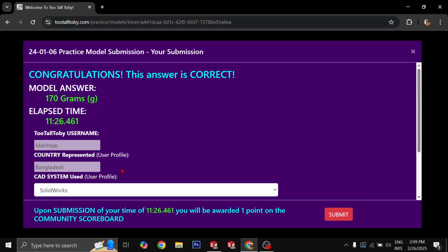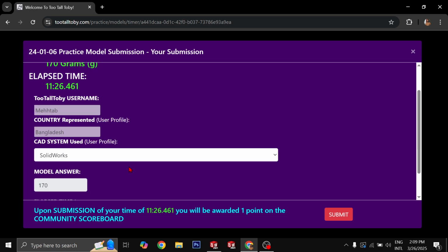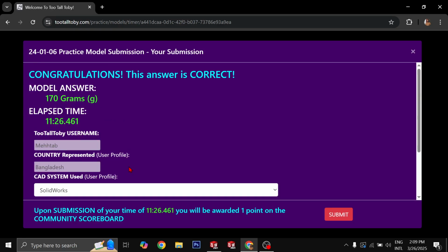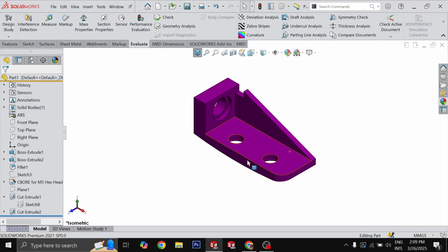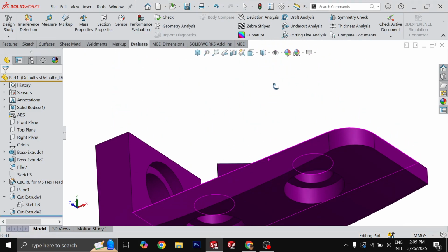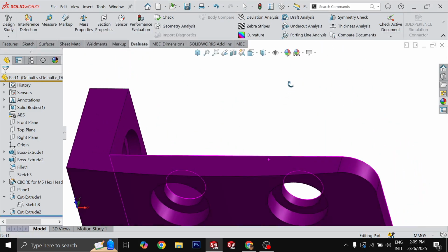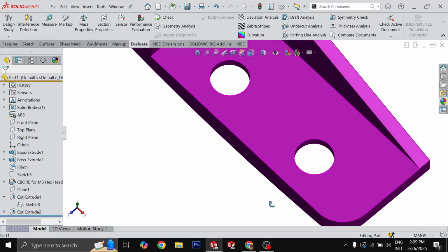So this was the tutorial. The trickiest part was to sketch those counterbores, which are kind of inverted counterbores. I didn't notice that at first. I thought simple counterbores, but that was inverted along the arc, so it was kind of challenging for us. But in the end, we just simply separated the counterbore into 2 features by using 2 circles of 20 and 30 and using the offset start condition.